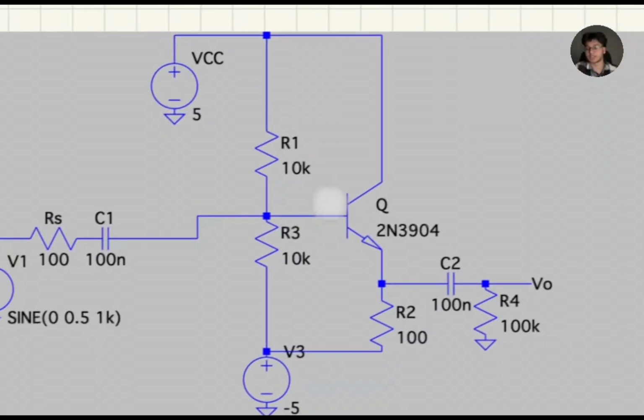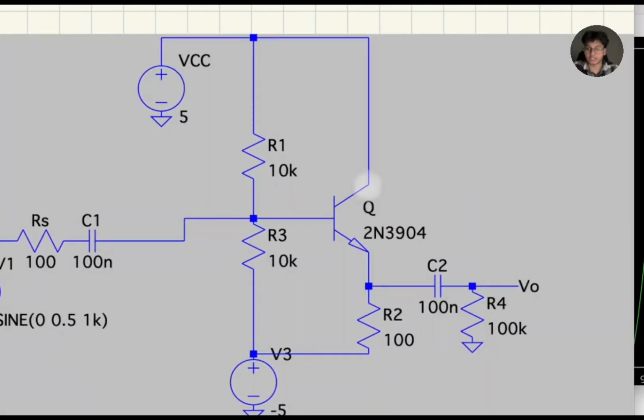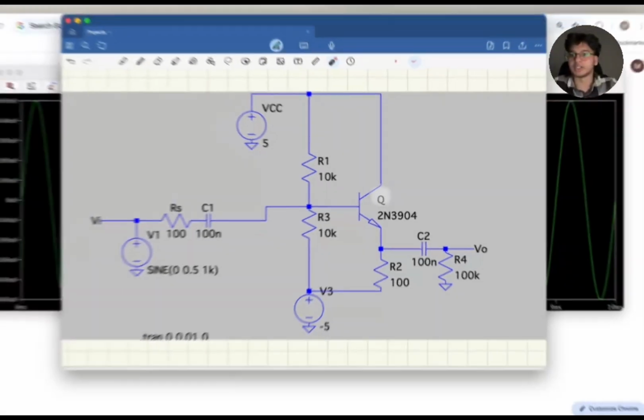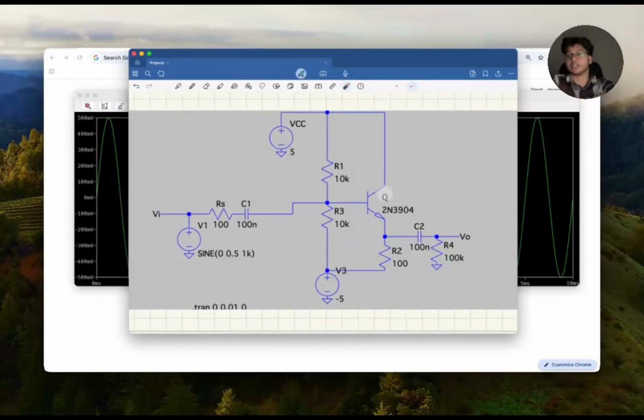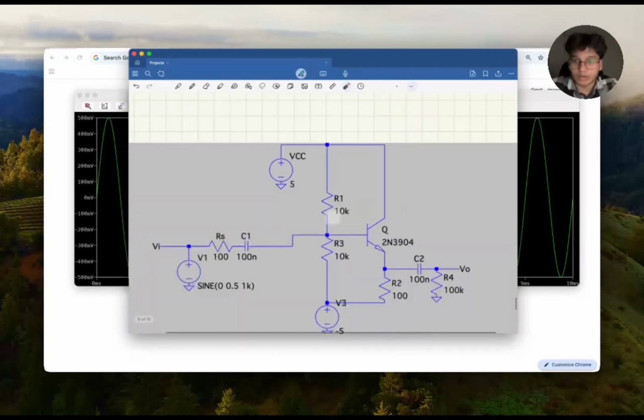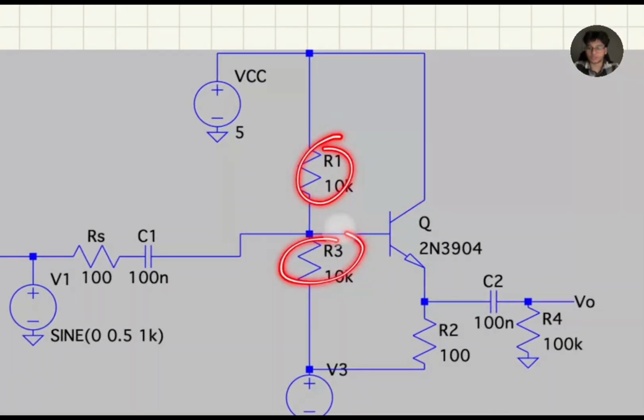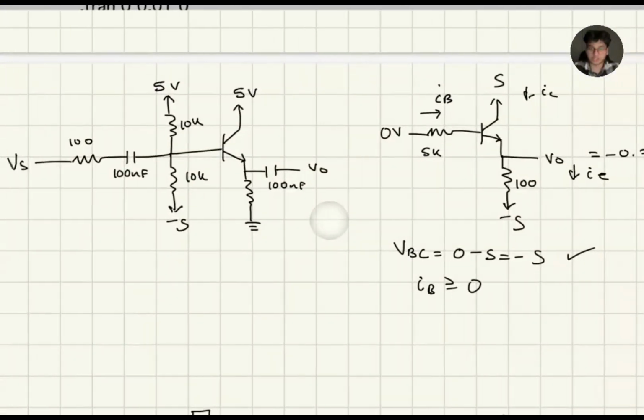In addition, the transistor that I used is a BJT, and I used the NPN because it has really good linearity and it doesn't struggle with switching voltages, like turning off and on really quickly, which is good for the frequency that we're going to use. We're going to use really high frequency, which I think is kind of necessary for this. Now, these resistance values I will explain further in the calculation, which is down here.